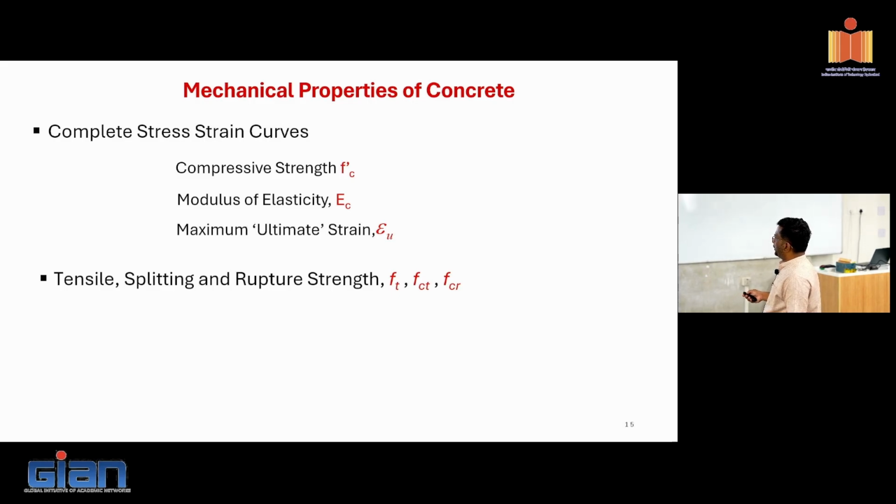In compressive strength, we usually call this f prime c, which denotes the cylinder compressive strength. In India, what do we use as a standard, cube or cylinder? Cubes, right? So why do we use cubes? Why can't we use cylinders? Just because it's easy to do, and we have been carrying forward the legacy from the Britishers. But actually, cubes will give you higher strength.